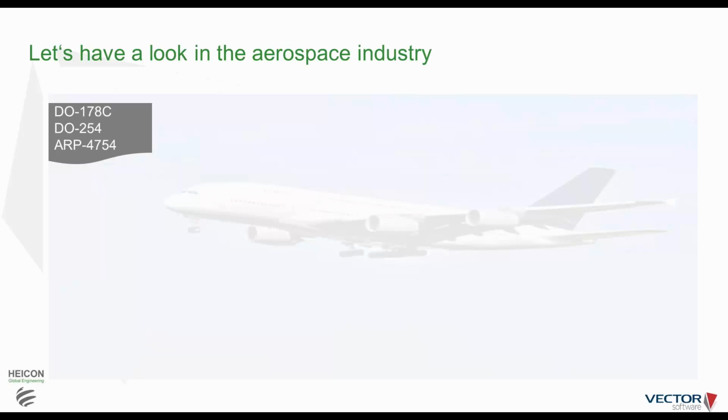In the aerospace industry, we have different standards, of course. ISO 26262 is one standard in automotive; it's roughly 3 in aerospace. DO-178C is for software, DO-254 for hardware, and last but not least, aerospace has lately ARP4754 and ARP4761, so a standard on system level. So they are, from my point of view, comparable. It's about software and system development processes, how they have to be considered, what has to be done, what has to be implemented.